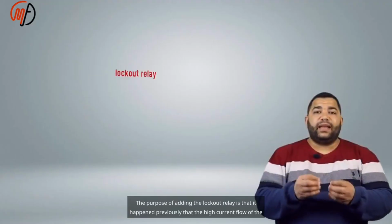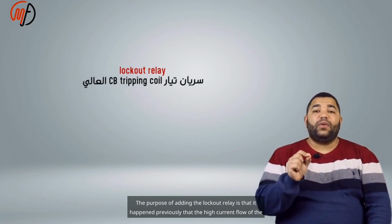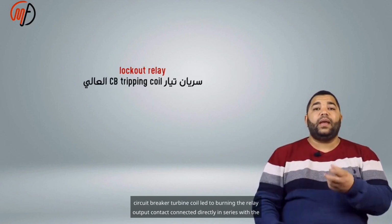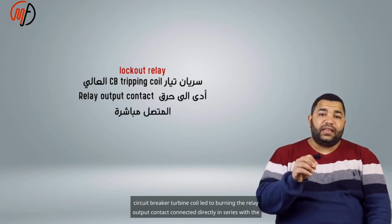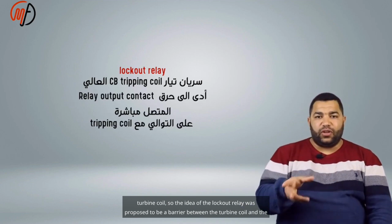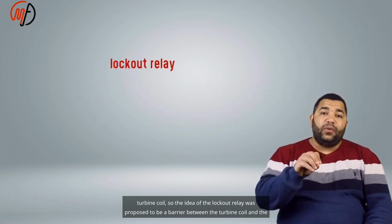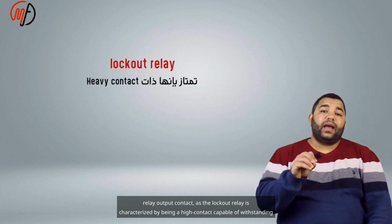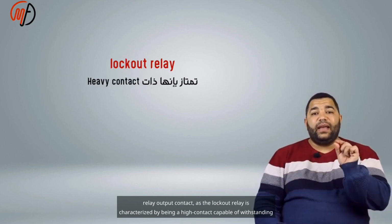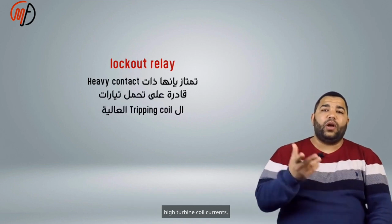The purpose of adding the lockout relay is that it happened previously that the high current flow of the circuit breaker trip coil led to burning the relay output contact connected directly in series with the trip coil. So the idea of the lockout relay was proposed to be a barrier between the trip coil and the relay output contact, as the lockout relay is characterized by having high-capacity contacts capable of withstanding high trip coil currents.